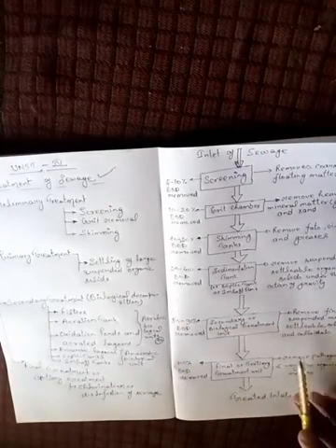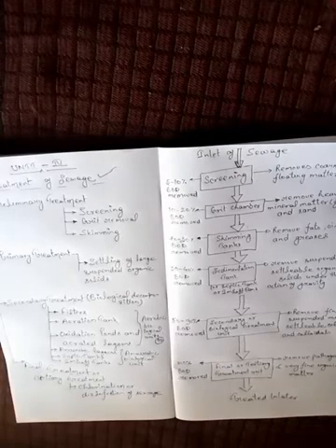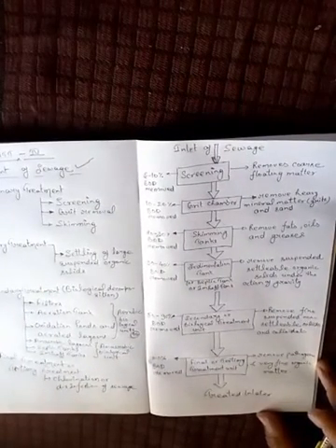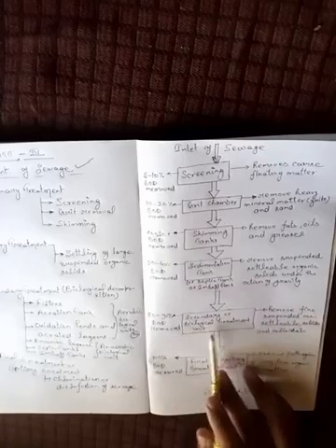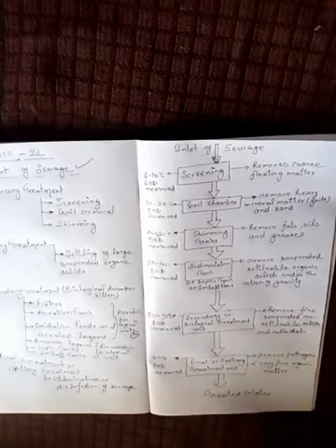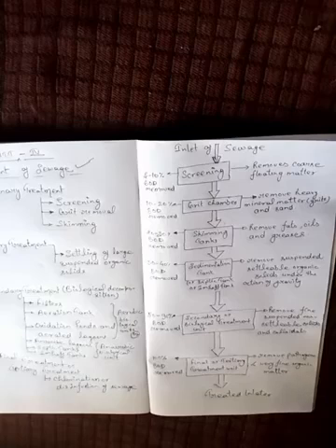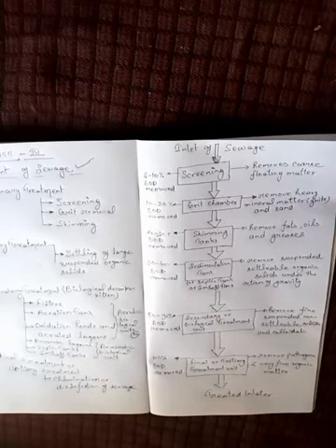The various structures used in this step are sedimentation tanks, septic tanks, Imhoff tanks, storage tanks, and settling tanks. These are the various structures used for the purpose of primary sedimentation. After that, the treated water goes to the secondary or biological treatment unit. In this unit, fine suspended particles which are non-settleable under the action of gravity are removed by various methods in which filters, aeration tanks, oxidation ponds, etc. are used to treat these types of impurities or particles.